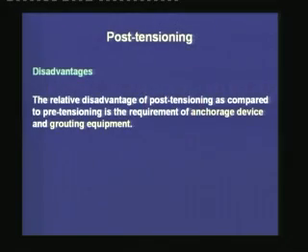Now, transporting this anchorage device and the supply may be a hindrance for a project which is in a remote area. And the second disadvantage is that for a grouted post-tension beam, the grouting equipment itself has to be transferred to the location where the tensioning operation is done. If the post-tensioning is done at site and if the site is remote, then transporting the grouting equipment is another necessary task for the post-tensioning operation.